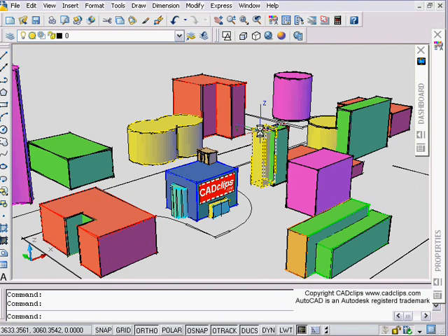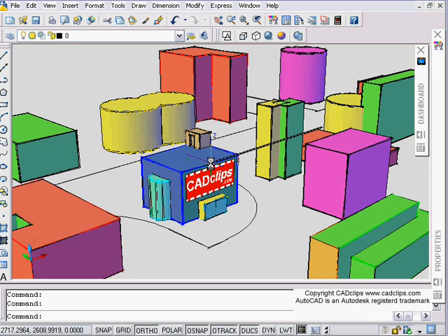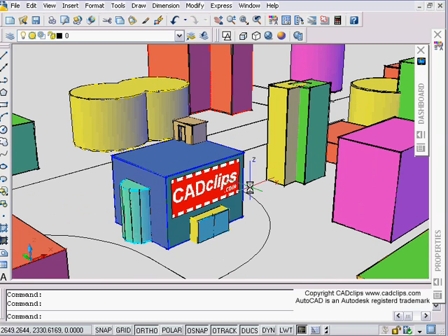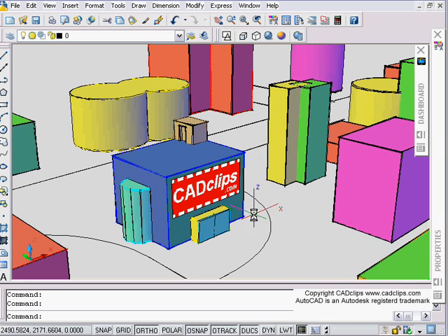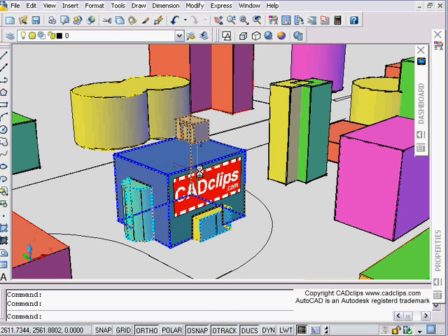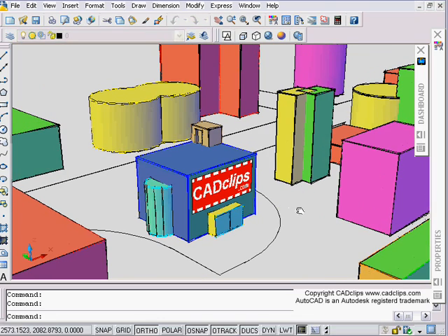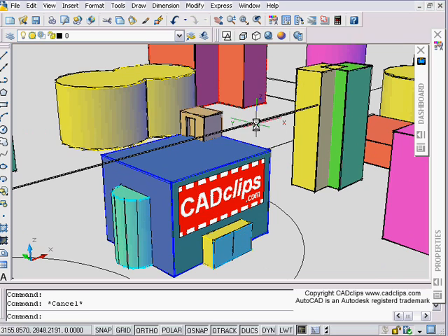So meanwhile, back in our AutoCAD, we're talking about the Copy Face tool, and the Copy Face tool creates a region of a face from some existing face or piece of solid geometry. After we have created and unioned our objects together, sometimes we want to create either a polyline or we want to be able to quickly get that face or that shape. And you can't really use the hatch command to do it, or the boundary command, so there's an intermittent step.